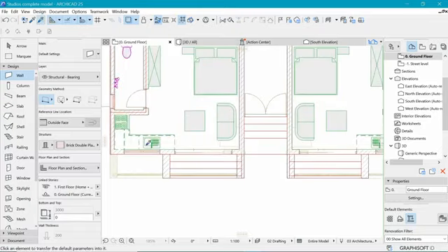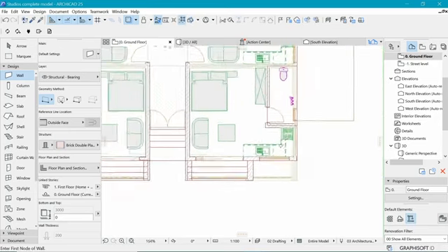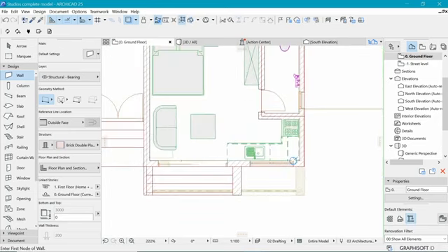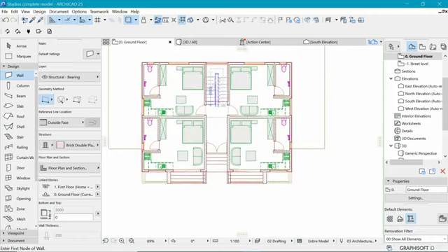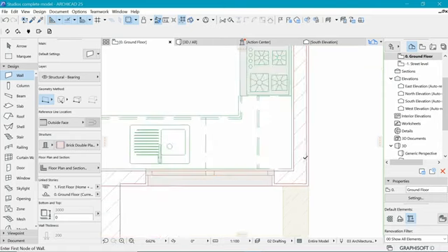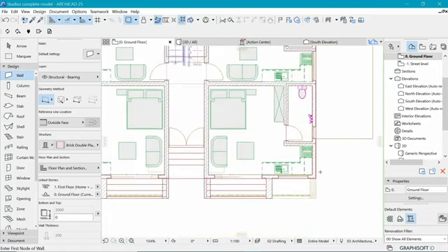Inject again in this other wall here, or the shortcut, which is Ctrl Alt click on this one, and you can see that the whole of these round walls have been changed to brick together with the plaster finish.